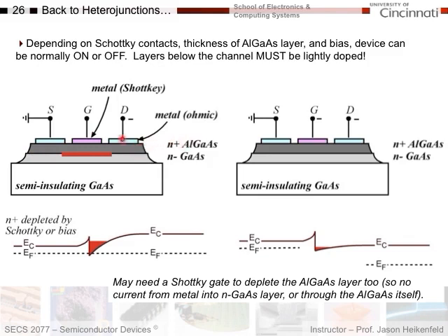This layer is really thin, so it's really easy to get current from the source and the drain down to the 2D electron gas layer. Once it gets in there, the mobility is extremely high, such that I get a huge amount of conductivity here. So getting current through the super thin layer and along this very high electron mobility 2D electron gas, there's almost no resistance. And so the R of my RC time constant for a circuit made of these is very low, because I've got my 2D electron gas.